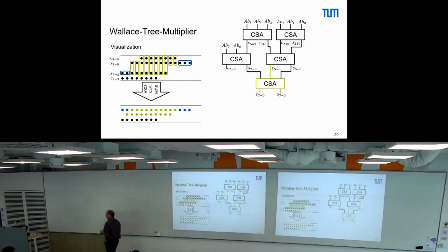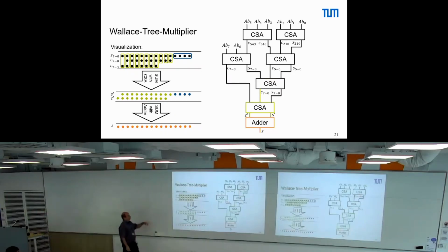So we end up in this new structure here, again 3 lines. So we add another carry safe adder, which compresses these 3 lines that are left to 2 lines. So from here to here, we have another carry safe adder, with 3 inputs and carry and sum outputs. This gives us an output that actually collects all the inputs and compresses them into a representation of the result with 2 bits. And now we need to convert this 2-bit representation into a 1-bit representation, which means we need a classical adder for all the sums and all the carries, and then we are done. Okay, concept okay?